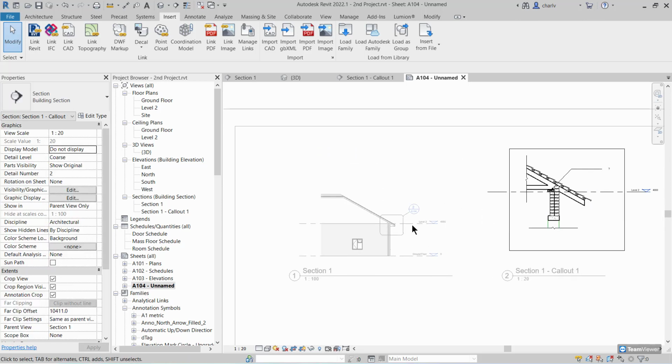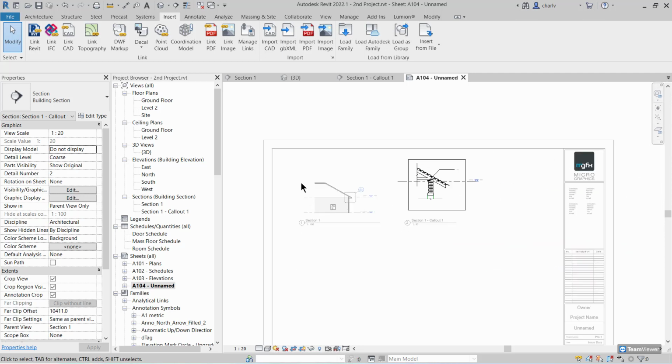All right, and then with the 3D modeling, don't over-model. Model objects just as generic items, and then spend the time creating the details. Okay, so that's the idea.